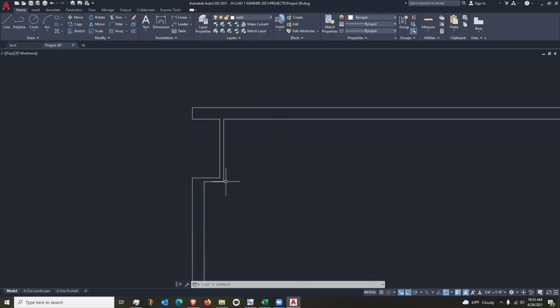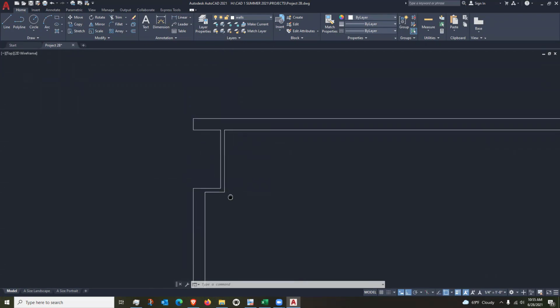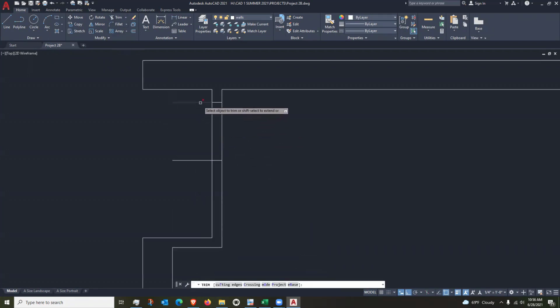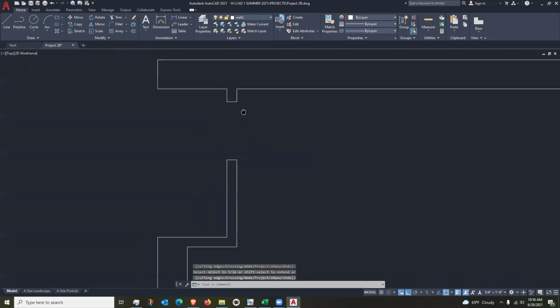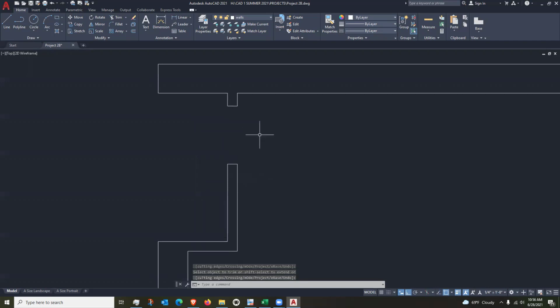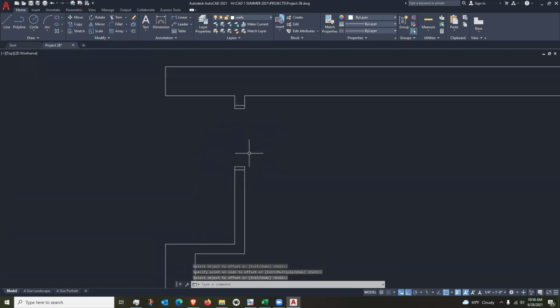So the door is 4'6" from this section of wall. So offset 4'6", and it'll be 3 feet wide. And I'll do some trimming here. And while I'm at it, I'll put little door frames on here. Offset door frames are 2 inches. Good. Next step, I'll add that door.